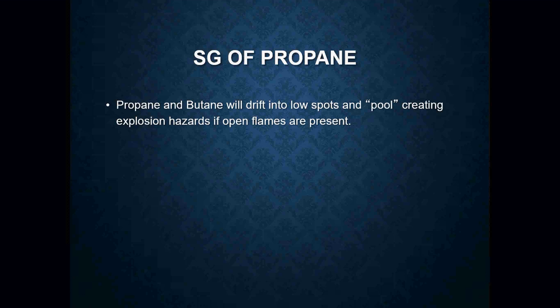these leaks. If you are installing your natural gas lines or propane lines, by code, you have to pressure test those lines with nitrogen, and you have to leave it for about 24 hours just to make sure that there are no leaks. If you fail to do something like that and there is a leak, you're the one that's going to obviously hang for it. But you do have to take those precautions to make sure that you are not creating some sort of explosive environment.